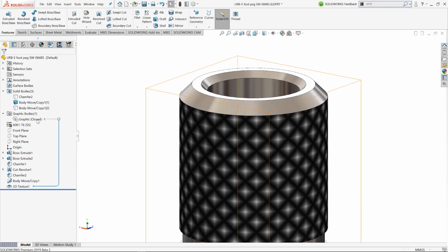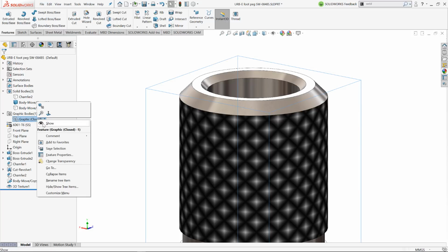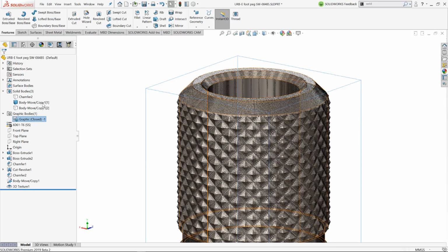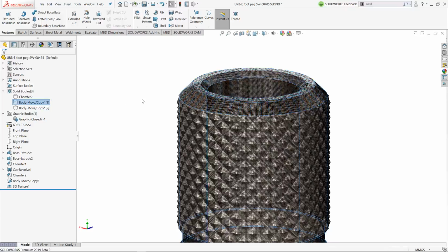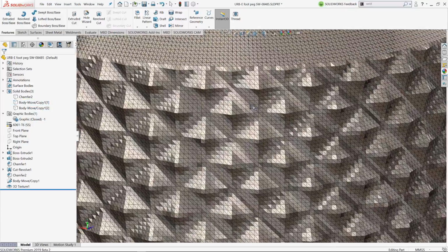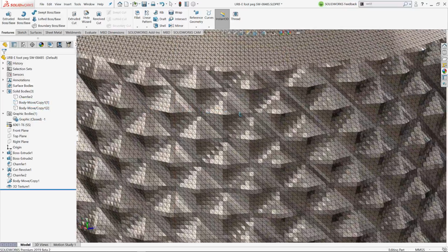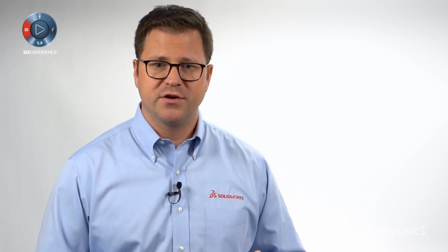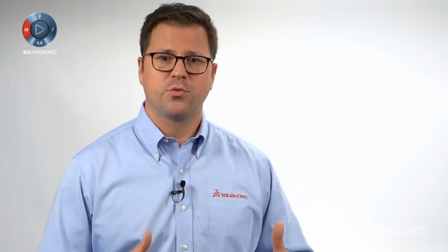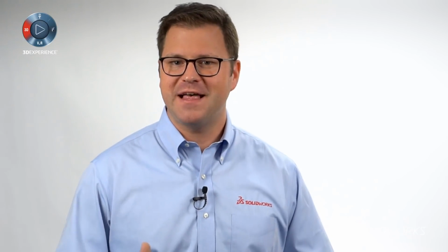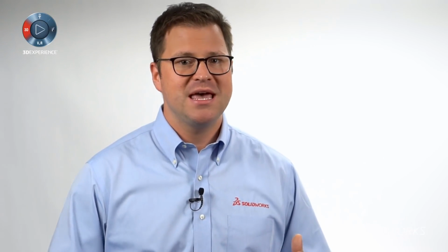3D texture requires converting the work body into a mesh body to apply the texture. The result can be saved right to STL for 3D printing. The original solid B-rep body is hidden. You can continue to convert to a solid mesh body and leverage the workflows enabled by 2018. Part modeling, it's all about the flexibility of creating geometry and speed in capturing accurate design intent.